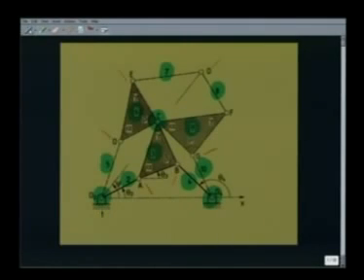Let us now calculate the degrees of freedom of this 10-link mechanism. We have already seen the total number of links n is 10. The number of kinematic pairs j is equal to, we have 7 simple hinges, namely at O, F, G, B, A, D and E. So, J1, that is 7, plus as already mentioned, there are 3 second order hinges, one at O2, one at O4 and the other at C. So, 2 into 3, that is J is 13.